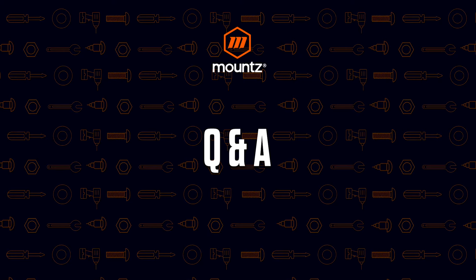All right. Next question, Dave, is on the screw presenter, how's the rotary wheel versus the other, V-shape? What's the advantage of one versus the other? So the advantage of using the automation style that has more of a turntable is that it allows the vacuum pickup to easily grab that fastener, and then the standard presenter with the bit guide allows you to take the tool with the bit and ride down the channel onto the fastener.